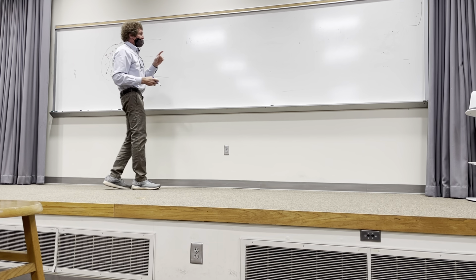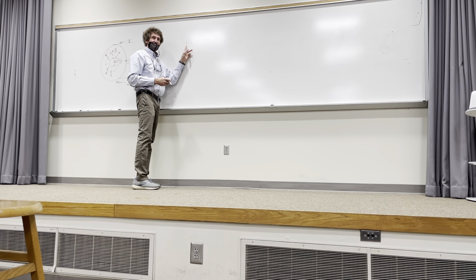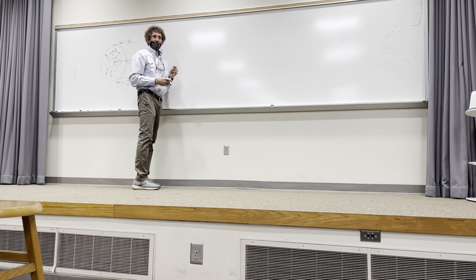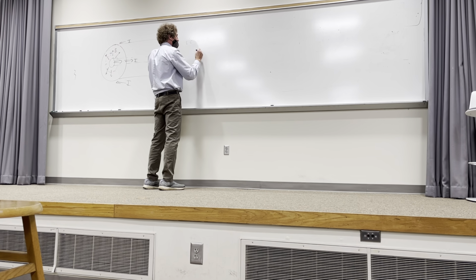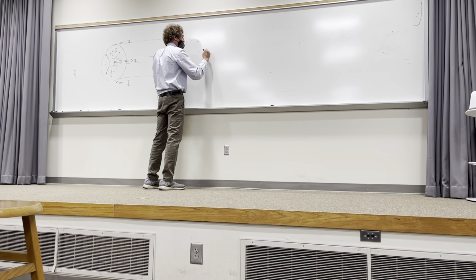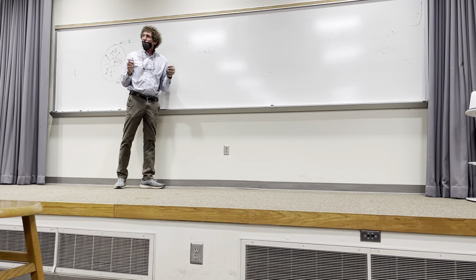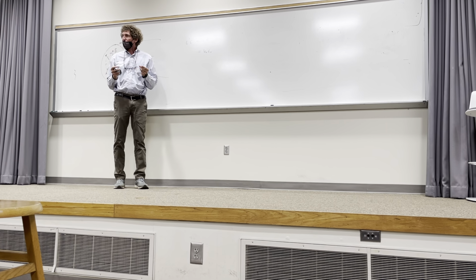So if you know the inductance per meter, you can get the capacitance per meter, and vice versa, assuming you know these parameters. Now that twin lead they're talking about has air as the dielectric, doesn't it? Yes. All right, so both of these for the twin lead will be mu 0 epsilon 0. Now, I don't know if you remember mu 0 and epsilon 0.